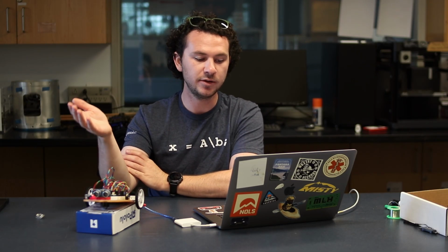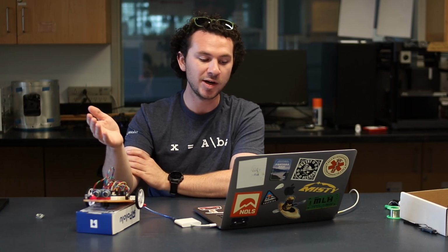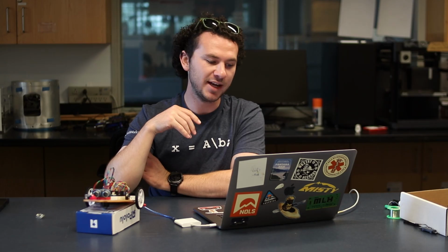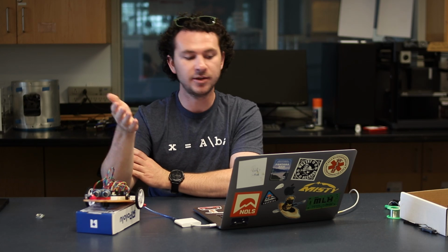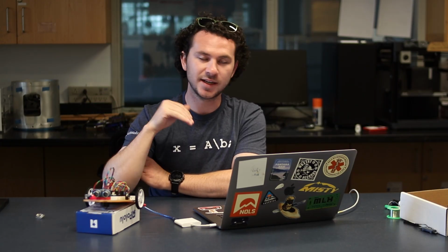Now that you've had the chance to go through this process with the magnetometer sensor, I would like you to try to do it with the accelerometer to interpret the direction of the gravity vector. So give it a shot yourself by filling in the get pitch function, and here's a little hint. Accel.acceleration.x will return the acceleration measured by the accelerometer in its x-axis.